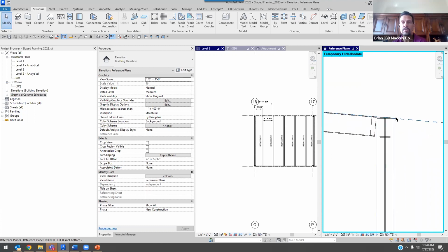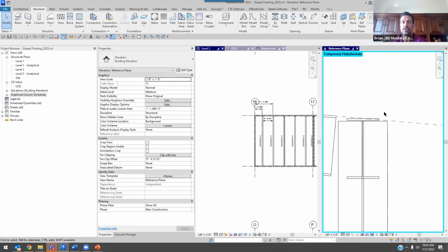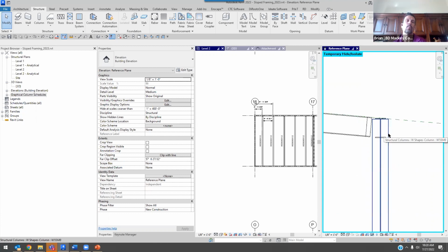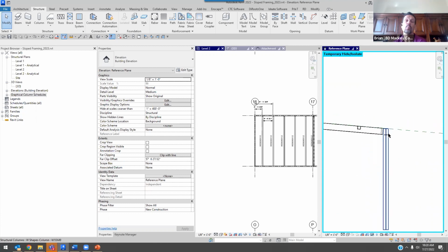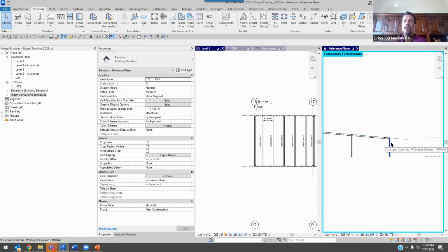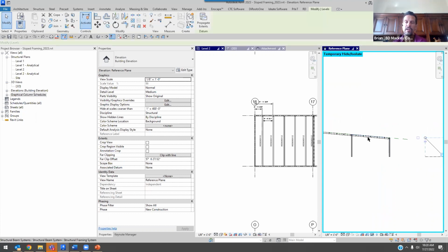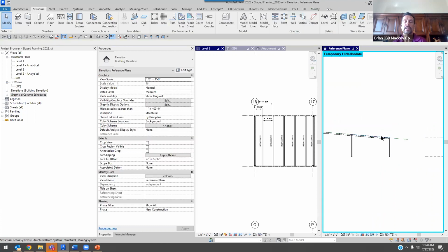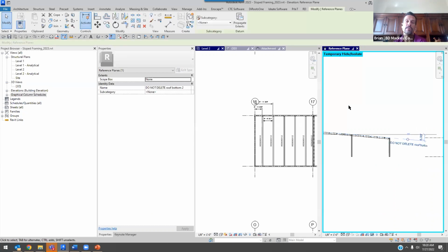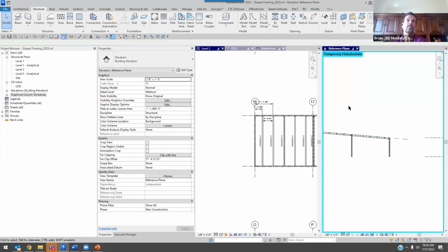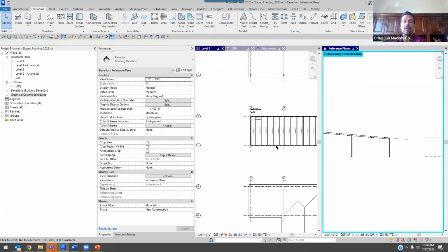I've undone a few times. It is critical that when you are rotating this, you pick the end of this column or whatever to make sure you're maintaining whatever that slope relationship was. Maybe you had a level there and I should have been rotating it from the level, who knows? But you've got to make sure that you are setting it up from its sticking point when you do it. But yes, absolutely could have modeled it all flat and rotated it.